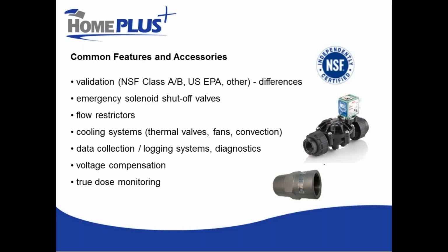And that validation does not have that flow rate limitation. Now, it's very, very common if you have an application that's beyond 30 gallons per minute, you may have multiple NSF 55 Class A units as opposed to one larger US EPA validated unit.